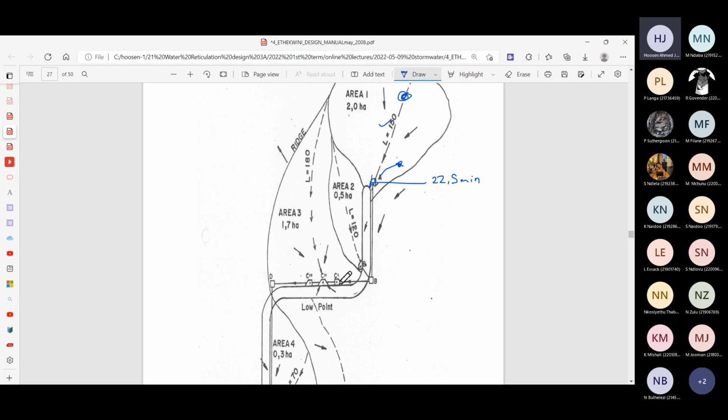Now, you might be wondering, but what's the C1 and C3 there? Just remember, I told you this is a critical point, right? It's a low point, it's a critical point. So those are additional catch pits provided to ensure that the flow does get into the pipeline and you don't get ponding or water flooding behind here to enter that particular catch pit. And so it's to ensure that you get proper drainage.